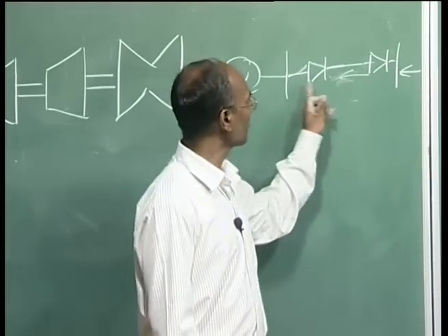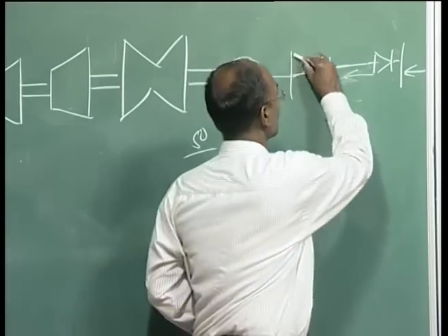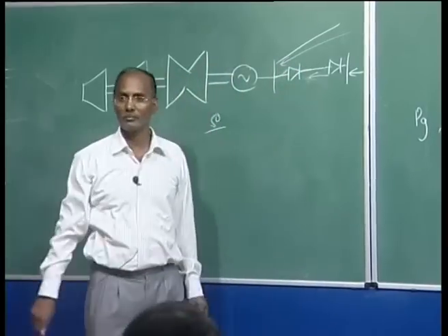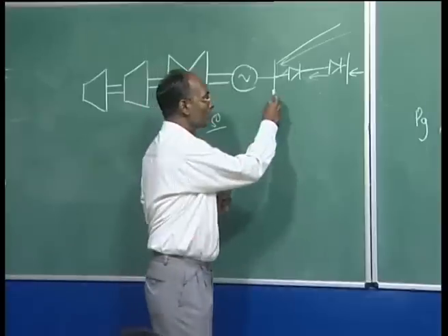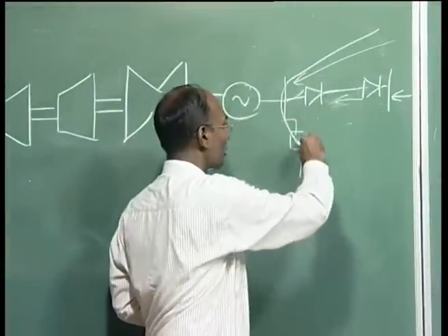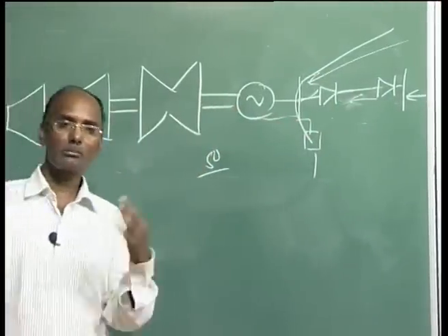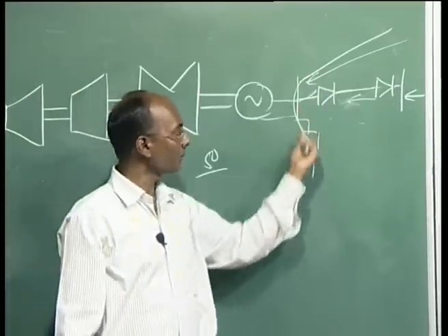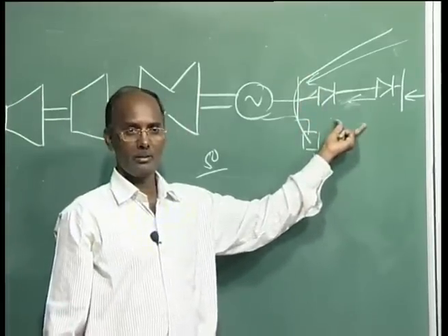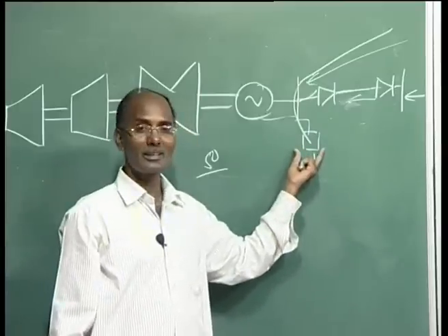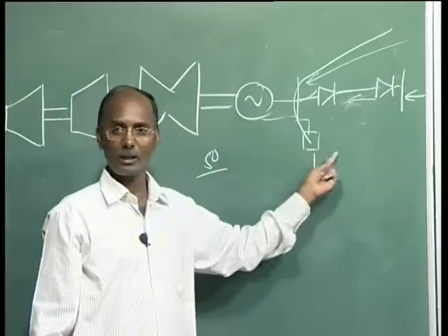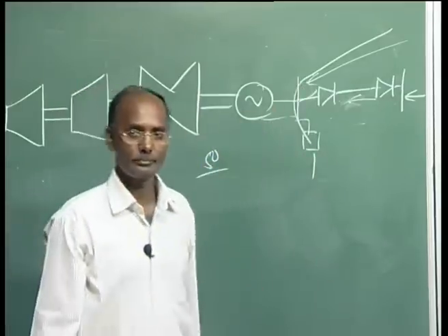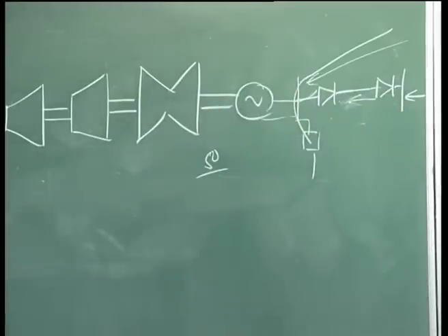It is not necessary that we use it like this, because we may have some AC lines also. So this may enter in this way. Or if you have an AC line and a DC line, and some filters here, then it may go down and may not enter here. So that possibility is there. If your filters are here, it may go down due to the HVDC link. But it is not always so, because we use the filters only for the characteristic harmonics. So for frequencies less than 50 hertz we are not bothering at all, so it will go inside. So this is your SSR control, which it can do up to a certain extent if it is properly designed.